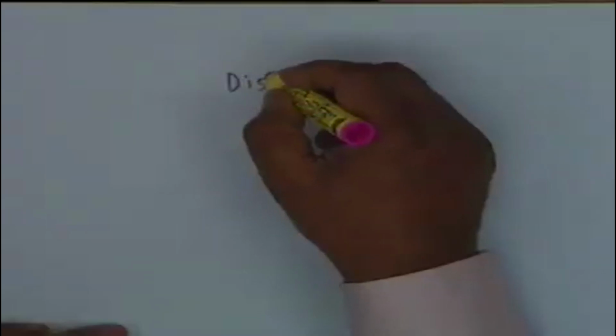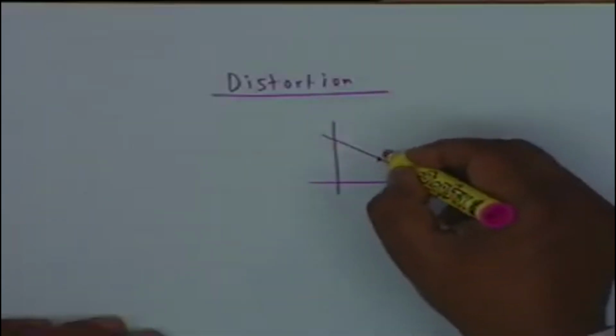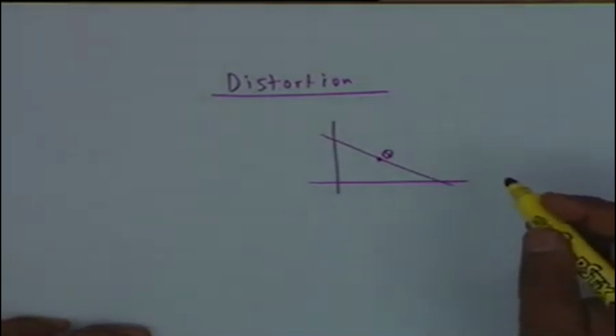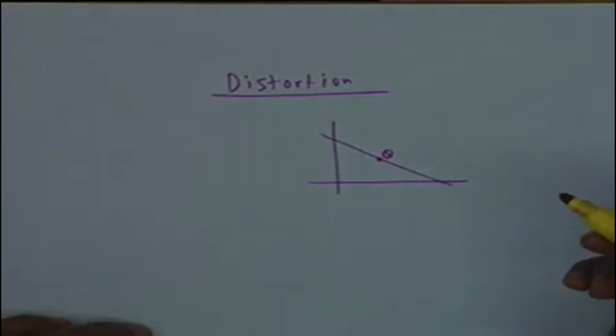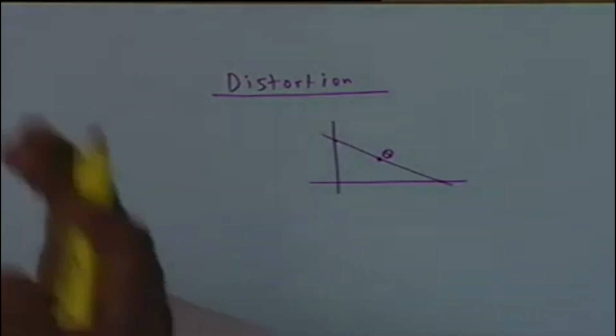Next we look at distortion, how it reduces distortion. Distortion cannot happen in small signal amplifiers. In small signal amplifiers, the signal excursion is around a small region around the Q point. There is no distortion. We have linear amplification. But suppose we take a large signal amplifier like a power amplifier, where the excursion is between the extreme limits, then obviously we reach nonlinear regions, and therefore there would be distortion.